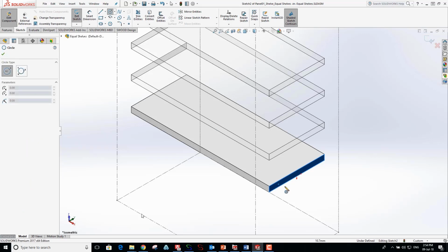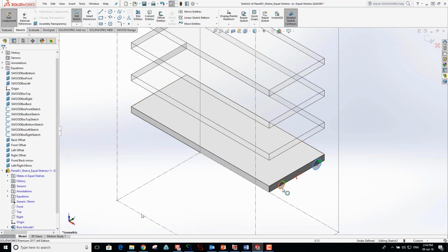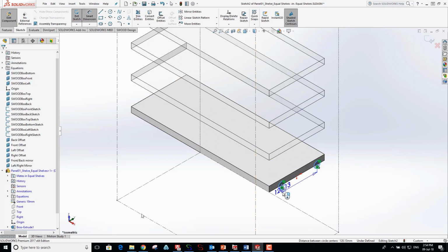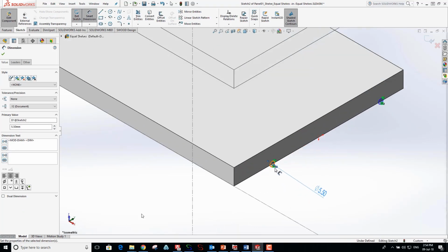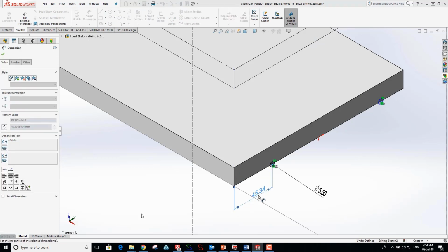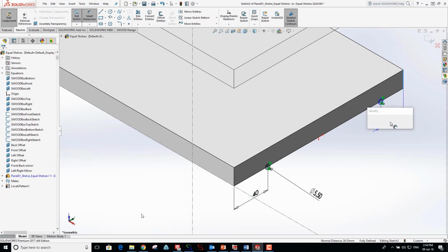So we're first of all working with some top-down assembly modeling techniques whereby we're editing the panels inside the SOLIDWORKS environment. What we're doing here to start with is just creating ourselves a sketch on the side of the panel, ready to create those cut extrudes that are going to be needed to locate the shelf studs inside of the shelves. So we just used a couple of sketch relationships there, particularly the equal sized one to control the diameter of the circles, and finally putting in some dimensions to control its location.